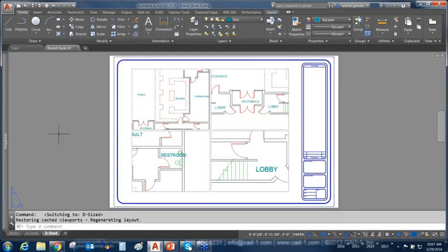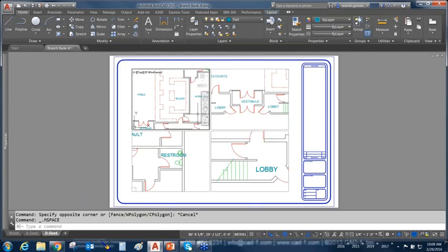Well, the problem arises when we flip on over to our new layout tabs in our paper space and we set up multiple viewports for printing our drawing. And the multiple viewports, now everybody has been using different scales for the multiple viewports, different plot scales. So when I set up a viewport inside of my paper space layout, then down at the bottom of my screen, I can set up a viewport scale.